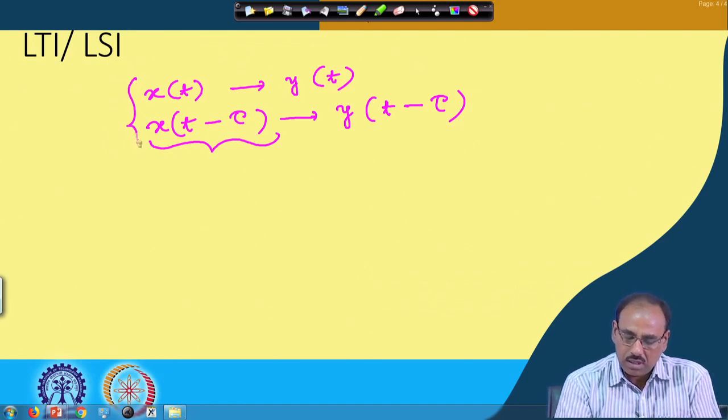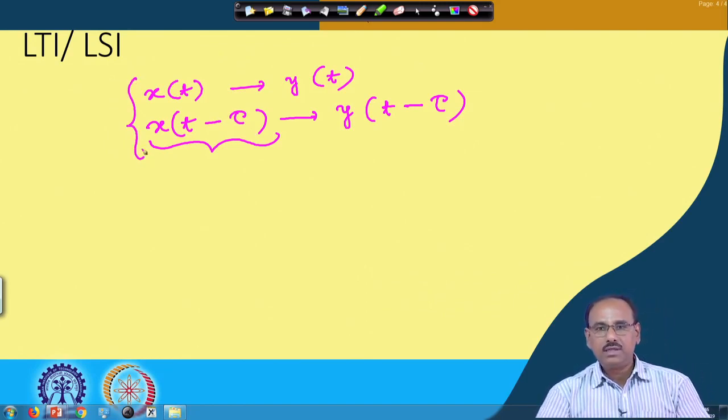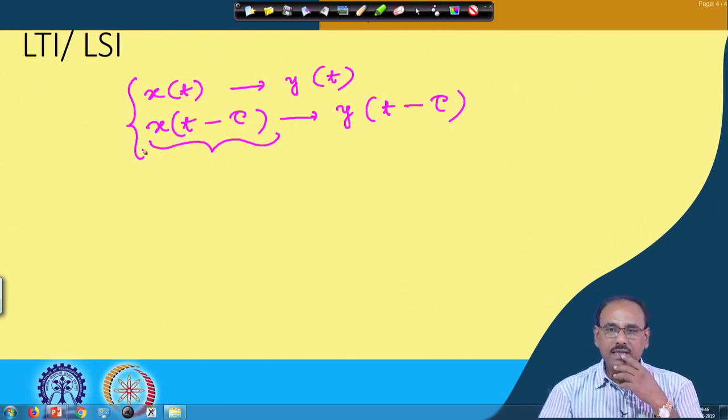So, this we talk about linear time invariant system when we are in the time domain, that means my input signal is a time domain signal, it varies with time. But when we talk about images, images are spatial domain signals where the intensity value or the color value varies over space. So, there instead of talking about a time invariant system, we talk about space invariant system, because our signal is a spatial signal, it is not a time domain signal.